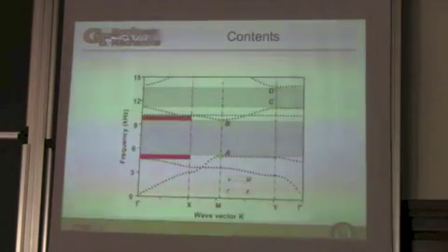All right, so I know we've seen a little bit of metamaterials, but this is a key figure, so I'm going to just step back and try to explain this. This is dispersion, so if you were looking at some homogeneous material, not a waveguide, not necessarily a rod, but bulk waves in a solid, then in this picture what you would see is frequency versus wave number. In this case we call it the wave vector. I'll explain the Greek symbols in a moment. But you would see the wave number on this axis and frequency, and most waves are non-dispersive. You would see a constant phase velocity equal to the group velocity and just a linear line. Now, guided waves, Lamb modes, and whatnot show non-trivial dispersion, much like what I'm showing.